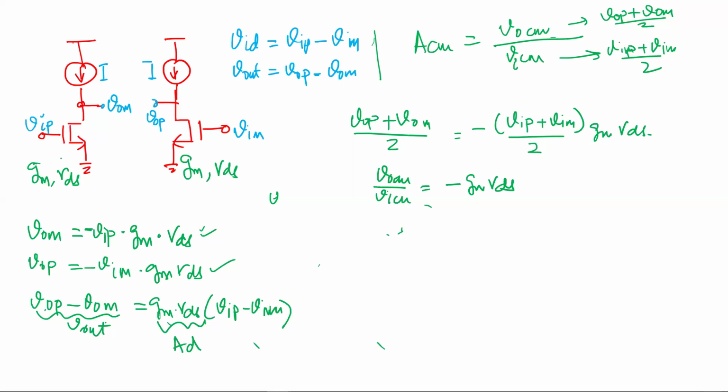I want, for example, you take an op amp in voltage follower mode, where you take the output, connect to the negative, and give a V in to the positive. What's the output? V in, right? It just follows. But the common mode is what? It's V in. Because if this goes by 1 volt, this common mode is also going by 1 volt, right? If I use this circuit, the output will get saturated. The common mode also will change and it will get saturated, right? So what can I do over here?